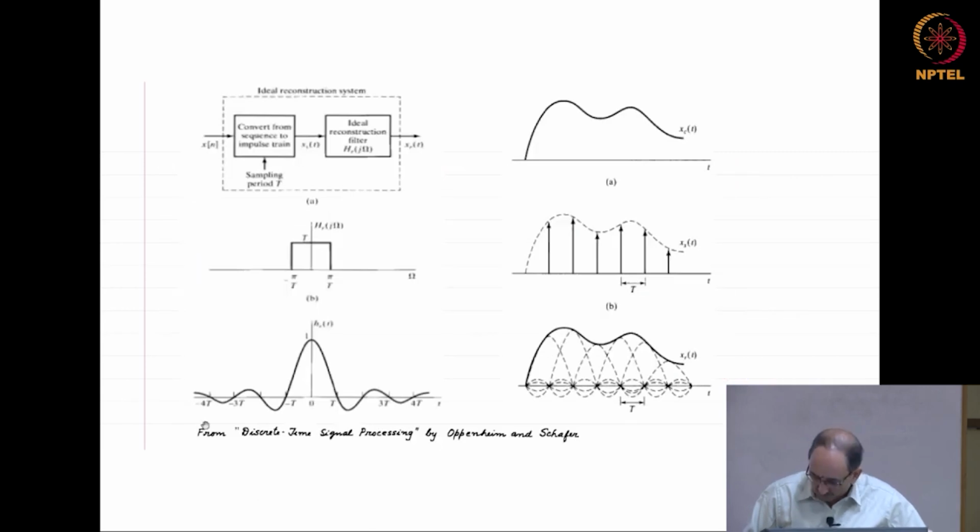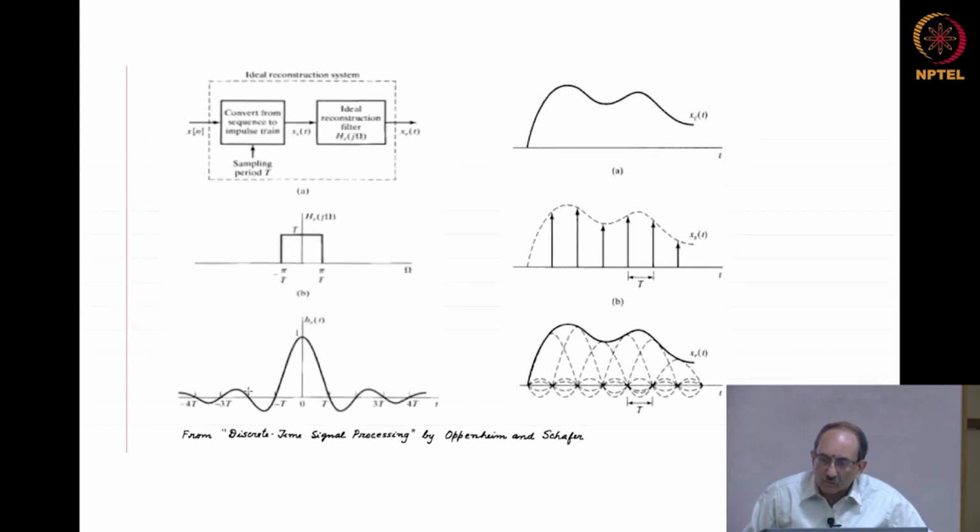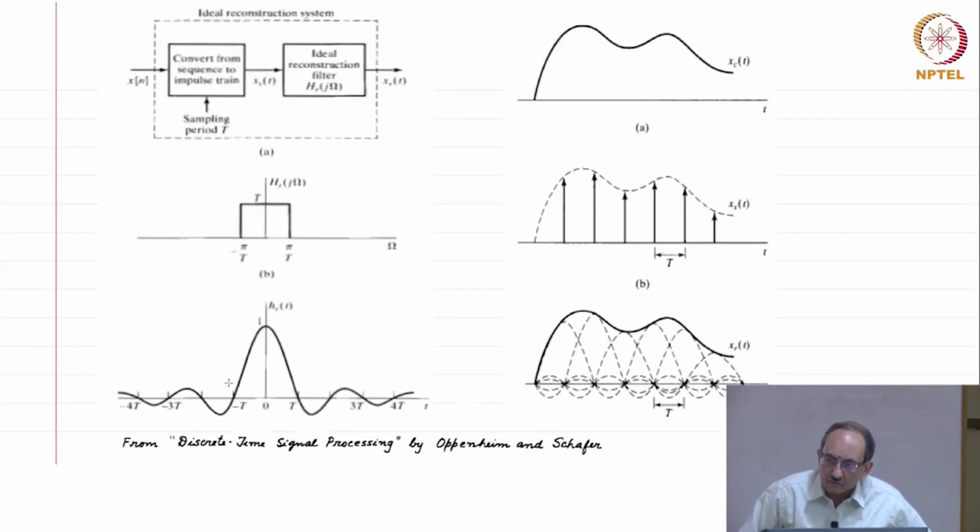Okay. So let me see if I can, so this is the underlying continuous time signal. These are the samples. Each sample elicits a sinc response like this. The only difference is the location of the sinc and the amplitude of the sinc. Note that when you consider this particular sinc, every other sinc goes through the 0 crossing at that point. In between they all add up to give you the exact curve without any loss of information. So this is how the theoretical construct behaves.